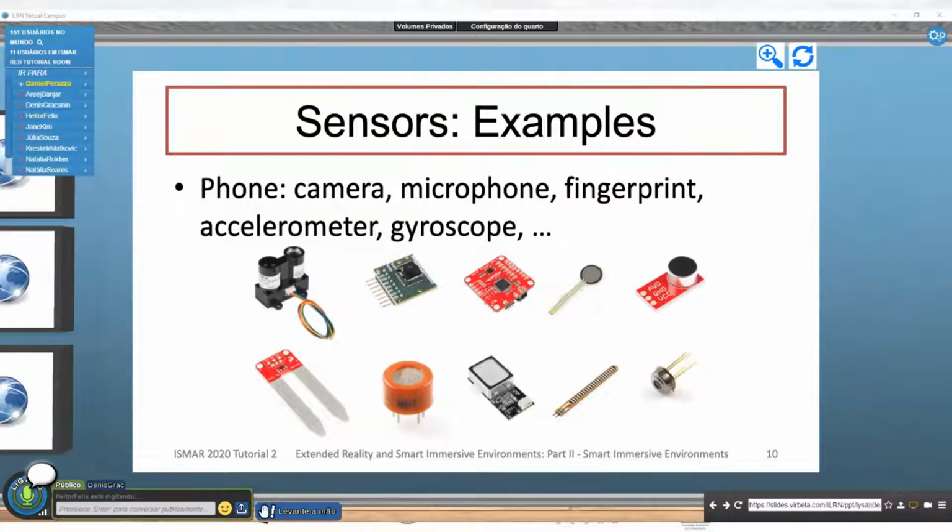So we have a fairly simple sensor that provides a single analog value, and we just need to process it. Then there are sensors that are in themselves programmable and require fairly involved low-level programming, usually using the I2C protocol.